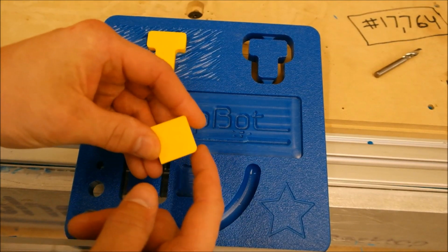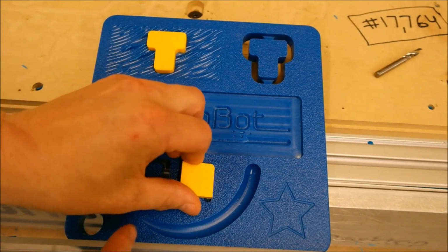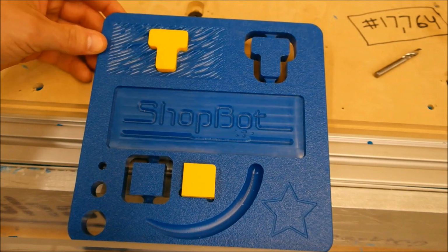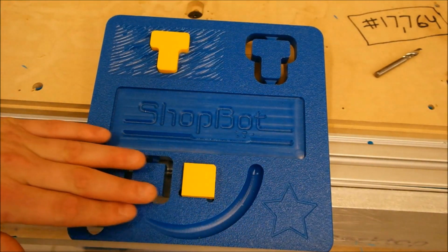Pretty neat feature, those fillets. And really nice to have the tolerance in there too. So remember offsets, remember fillets for whenever you have a male or a female profile pocket that needs to go together.